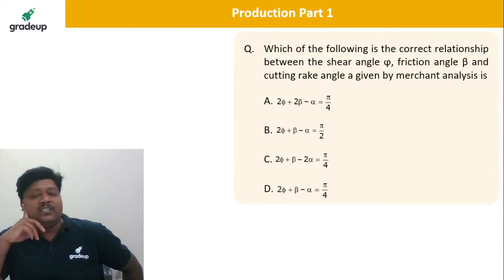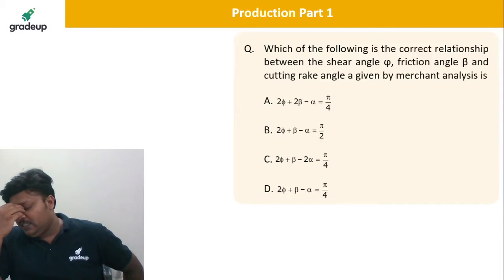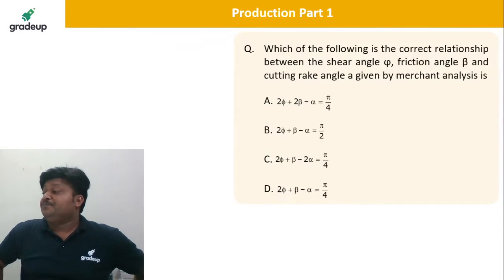With higher cutting velocity, tool life is affected, but you get good MRR and good surface finish. However, the wear and tear of the tool is quite high. Please remember this.